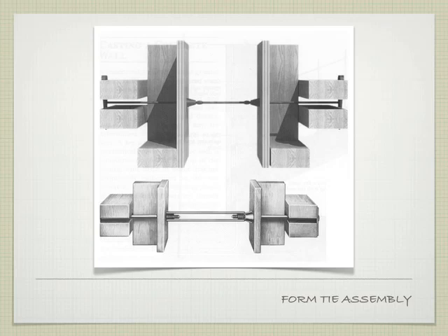The purpose of that little groove is, after you take the formwork away, you don't want to have a concrete wall with all these metal pieces sticking out. So what you do is you come in here and you basically snap off the ends of these two metal pieces, which is why there's that little groove, because that's where it's going to snap. Afterward, it's going to leave these little plastic cones in place, but you can pull those out, and then you can fill them. And I'll show you an example of that in just a second.